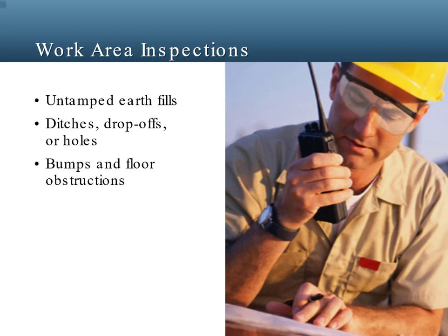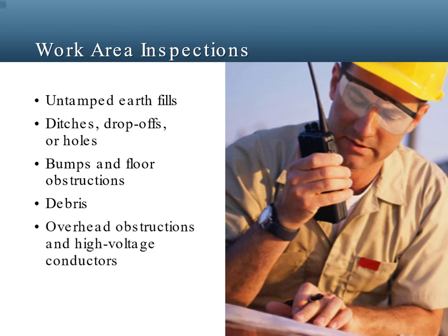Watch for bumps and other floor obstructions. Be careful not to drive over these obstructions because they can impact stability. Look out for debris and other things such as grease or water that could result in loss of stability. Finally, be especially careful of overhead obstructions and high-voltage conductors. Look for them and remember where they are. If there are any overhead obstructions, consider having a spotter on the ground who watches as the operator moves the aerial lift. And be sure the spotter has an effective way to communicate with the operator.